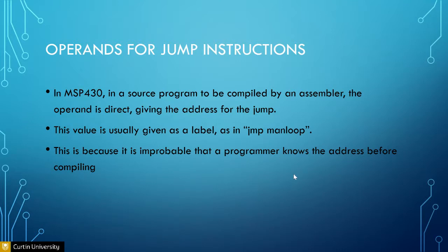So jump main loop. It's called main loop. Probably a typo error. Now when you jump main loop, this instruction does not look into even the carry bit. The flags are not looked at. It's straight away you jump here. So this instruction does not carry any operand or flags or condition.